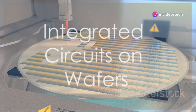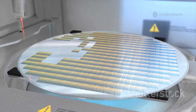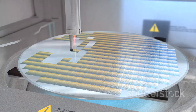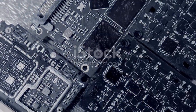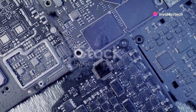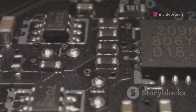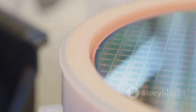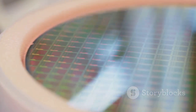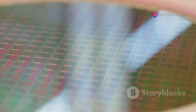The next stage in semiconductor manufacturing involves building complex integrated circuits on the silicon wafers. An integrated circuit, or microchip, is a collection of millions or even billions of transistors, resistors, capacitors, and other electronic components interconnected on a single chip. The process begins with photolithography, which uses light to transfer intricate circuit patterns onto the silicon wafer.